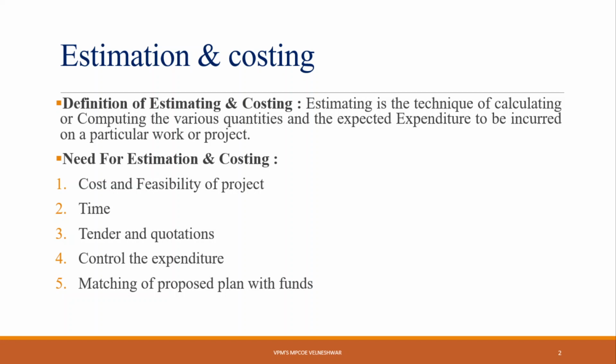First we will do work for only 20 lakhs, then we will submit one RA bill, and after that we will get another amount, and with that amount we will do the next 20 lakhs of work. RA bill means running account bill. In estimation, you can take the bill as a whole, or you can take the bill in parts. The part bill is called an RA bill. This technique you can also use.